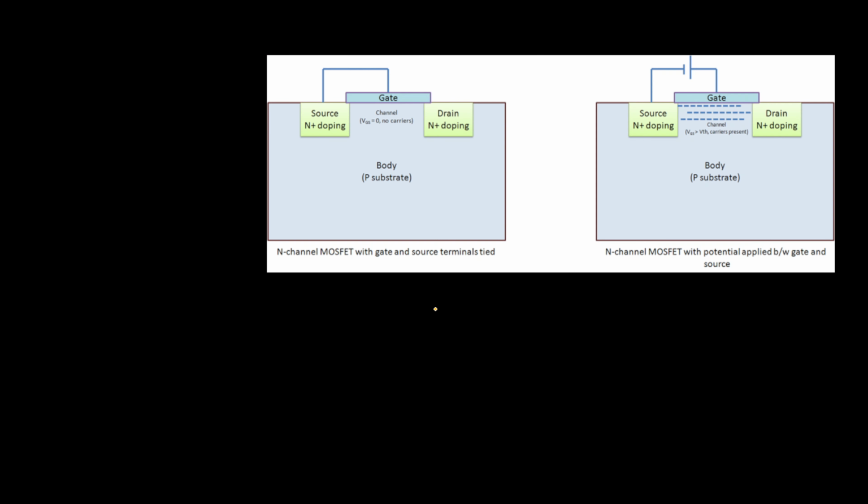So with that said, let's talk about what a MOSFET actually is. So MOSFETs are actually of two types. The first type being the depletion, and the second type being an enhancement type. So, like you can see here, let's take an example of an N channel MOSFET. So, an N channel MOSFET has an N doped source and N doped drain, along with the majority of this part being something called the substrate, which is made of p-doped semiconductors.